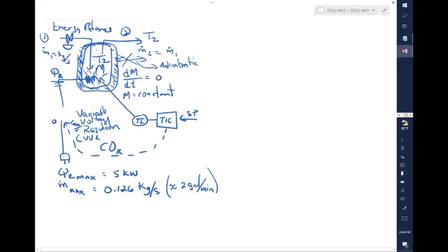So now here we have material getting into the vessel, but material also gets out of the vessel, and we also have heat getting into the vessel. So how do we do this energy balance? Well, that energy balance will be whatever is getting in. Let's write that down. Let's say that's going to be M1 times the heat capacity of the fluid times the temperature in. Let's call this the temperature in T1, minus some T reference.